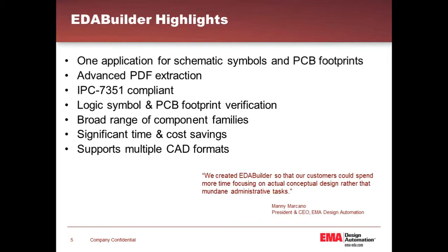So as I had mentioned earlier, CAD vendors typically have 2 different editors for schematic symbol and for PCB creation. In our case, EDABuilder is one application that allows PDF data extraction, the creation of pin tables, and pin tables are really the heart of this. It almost goes back to that Excel spreadsheet type form that can then be automatically partitioned into the logic symbol or done interactively.